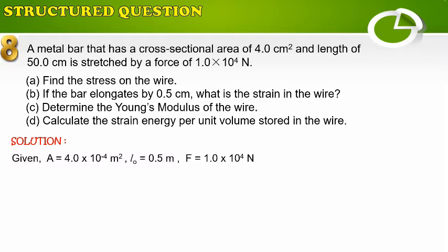of 50 cm is stretched by a force of 1 times 10 power of 4 Newton. For question number 8a, we need to find the stress on the wire. So referring to the given information from the question, we can calculate the stress of the wire by using the equation of F over A.